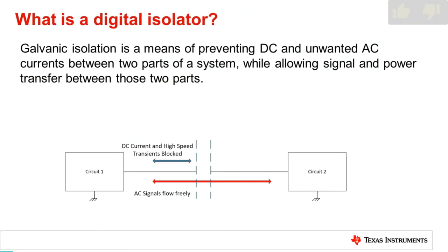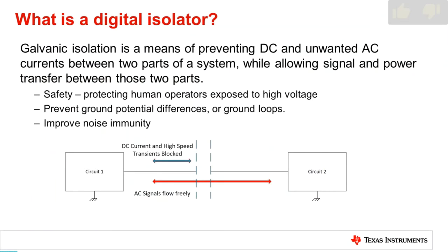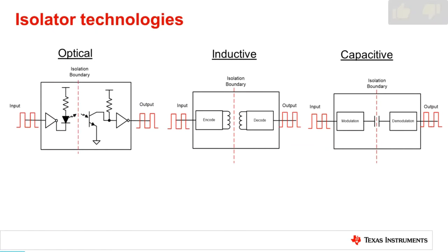What is a digital isolator? Galvanic isolation is a necessary form of protection for all electronics that interface with humans or other circuits in the presence of possible high-voltage events. In the case of human safety or even electronic protection, a high-voltage event can range from tens of volts to kilovolts. Over the past several decades, the technology used to isolate circuits has moved from optical-based optocouplers to silicon-based, with the digital isolators being the preferred choice for more and more designers.